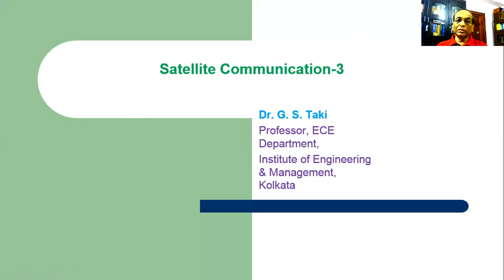Today we will discuss the frequency used in satellite communication and its band designation. The frequencies used are divided into several bands. We will talk about the band designation, the advantages and disadvantages of those bands, and the allocation of the bands in various uses.